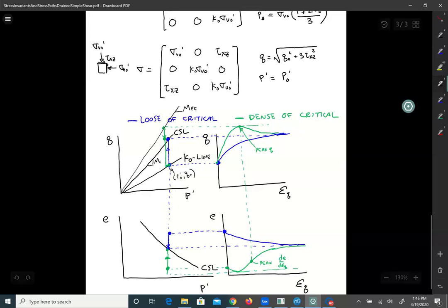So what that means is the stress path has to go up above the critical state line and then come back down to it. So it goes up to mobilize this peak friction angle at that point. Let me trace the path with my highlighter here. It's going to go up initially, and then it will come back down to here. That did trace it. So up to the peak, then back down to critical. And as it disappears, you can see the path that it followed.